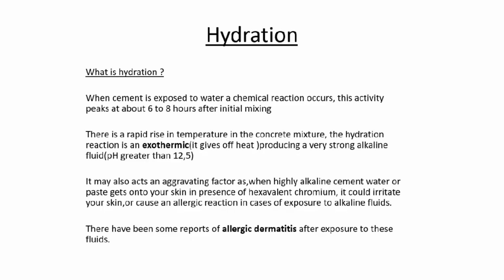Hydration. What is hydration? When cement is exposed to water, a chemical reaction occurs. This activity picks up from 6 to 8 hours after initial mixing. There is a rapid rise in temperature in the concrete mixture. The hydration reaction is exothermic, not endothermic. Exothermic means it gives off heat, producing a very strong alkaline fluid with a pH greater than 12.5.